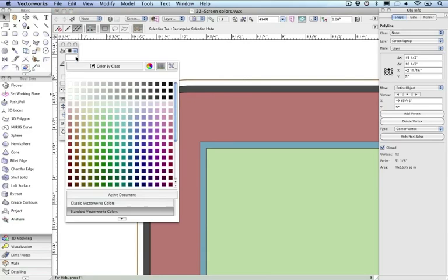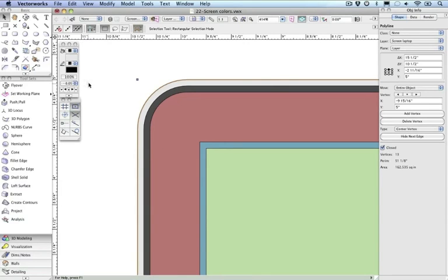If this display were to remain in 2D, the visual representation seen here would be fine. However, in 3D, we're going to need to apply a different thickness for each colored polyline. For this reason, we cannot have the polylines overlapping each other. So next, we'll clip the polylines to remove any unneeded or hidden geometry.